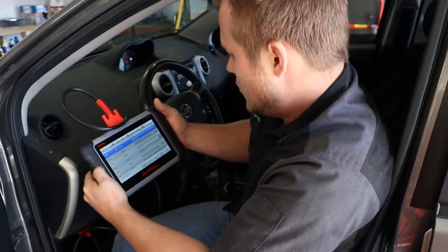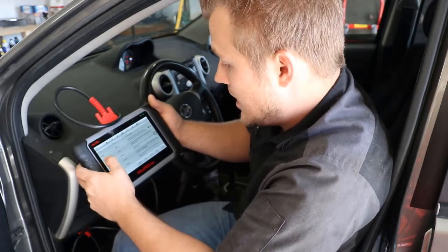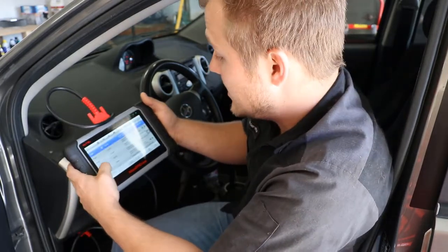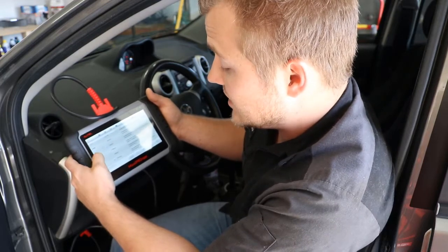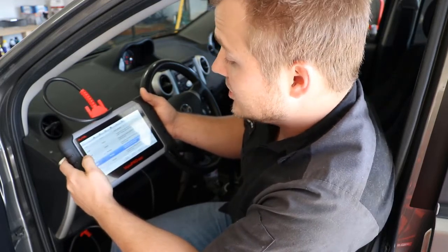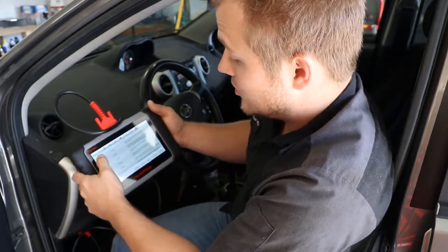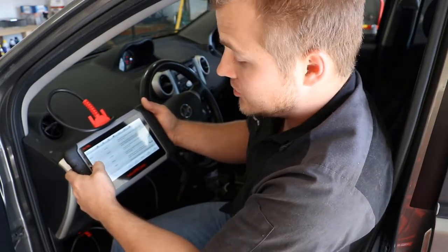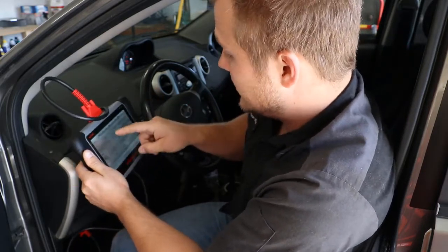Alright. We have, oh boy, okay. This is actually a pretty common problem for the Toyota Scions: the Evap leak. I have codes P0441, 442, 446. Some of these codes are in the history, some are pending right now, and some are current. So we actually only have about 3 codes here: 441, 442, and 446. So we're going to look up those codes and search what they are exactly.